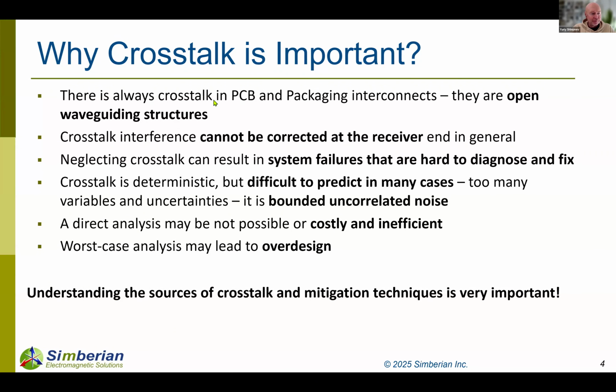Why is it important? Well, first of all, PCB and packaging interconnects are open waveguiding structures. I keep repeating this because it's not obvious, and I put a few slides and even a little demo of the fields later in this presentation, just to explain what I mean by open waveguiding structure. So it cannot be corrected at the receiver in general.